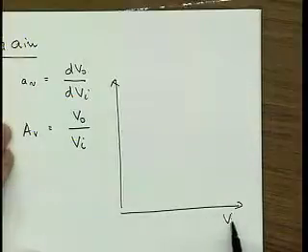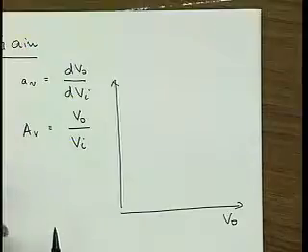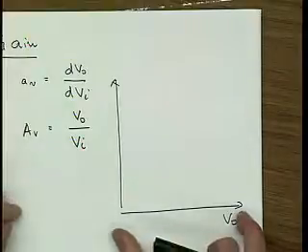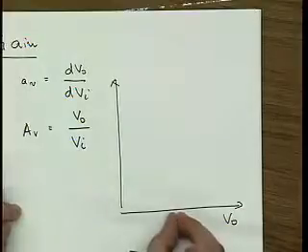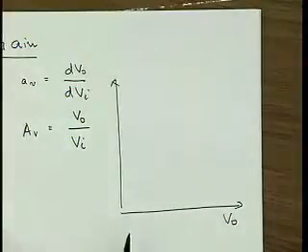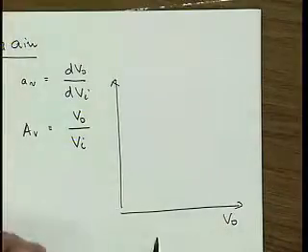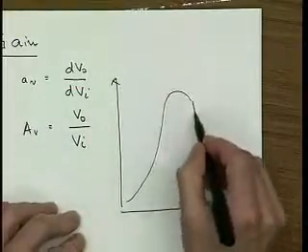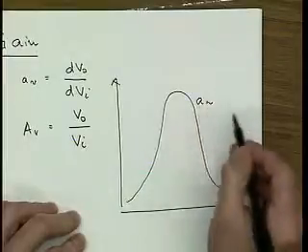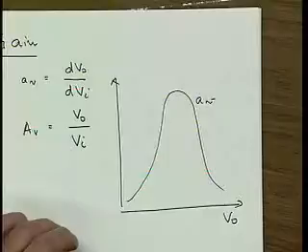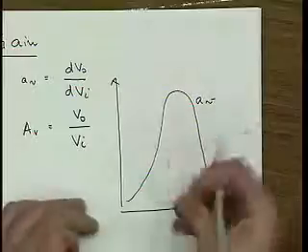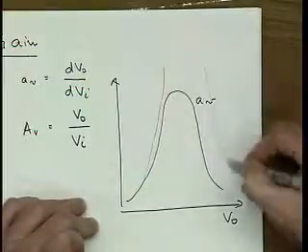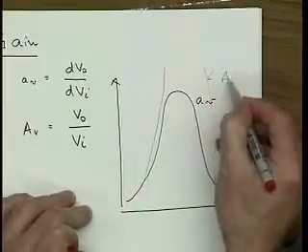I usually plot them as a function of Vout instead of as a function of Vin. Why? Well, because most of the time the amplifier really has a high gain, and then Vin would be 5 microvolts, and Vout would already be 1,000 volts, or something like VDD. So Vout is usually the better parameter to use on the horizontal axis. And so here are these two gain metrics. There was the open loop small signal gain, AV, like this. And then there was also the large signal gain that looked something like this. That was AV.